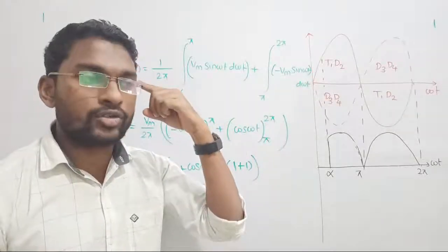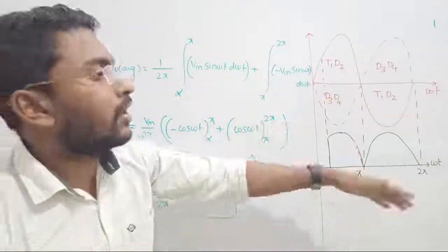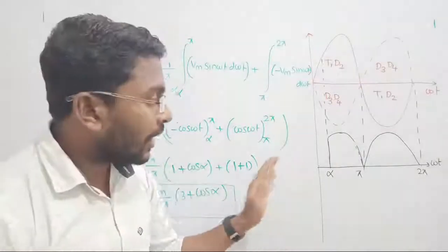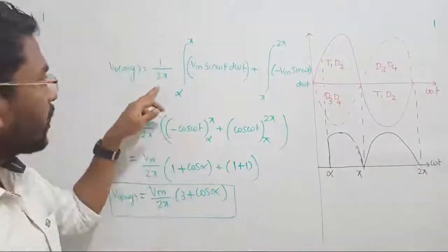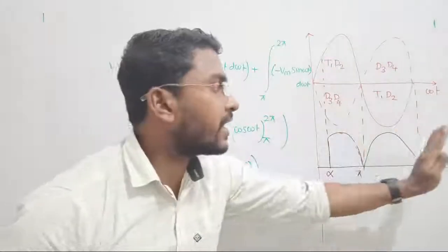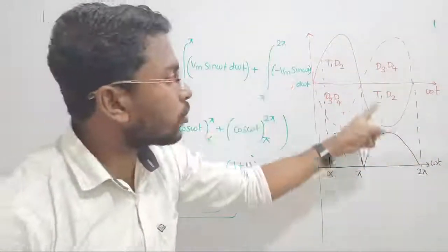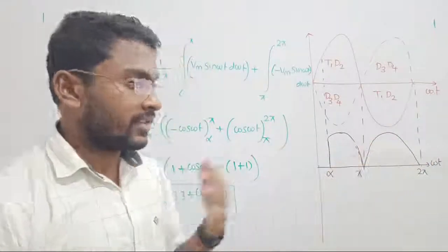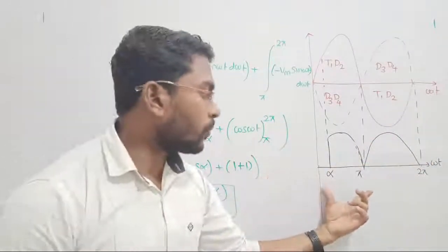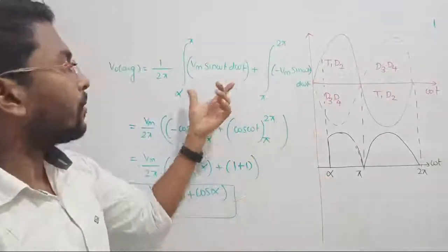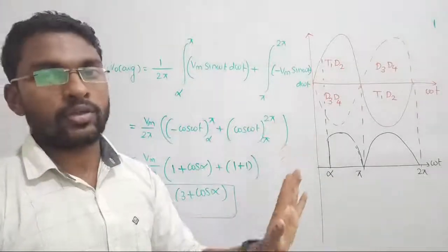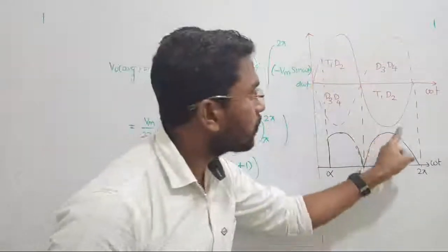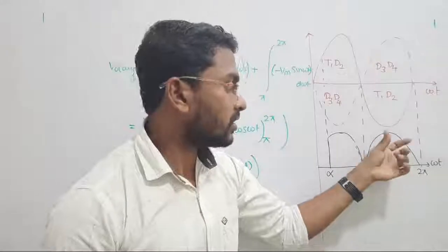Understand, you should think about this logically. Sir, so wherever the wave goes up, should we put minus there? Not like that, I never said that. What I am saying is that I have taken the total cycle. How much period are you taking? You take 2 pi. In one complete cycle, when you choose sin omega t, this is your original waveform. But I am not getting that one, the opposite line has come. Suppose my period is only 0 to pi, then I can very happily go with Vm sin omega t. But in the cycle I selected, the nature of the sinusoid is not this, I am getting this one, that's why I am putting minus.